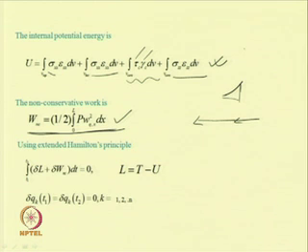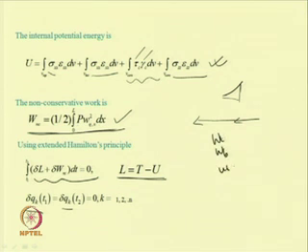Now, by using these terms in the extended Hamilton principle, which is written as the integral from t_1 to t_2 of delta L plus delta W_nc dt equal to 0, where L equals T minus U, and taking q_k as the generalized coordinates which vanish at t_1 and t_2, one can find the equations of motion. So, now one can find a set of equations of motion in terms of w_t, w_b, u_t and u_b.